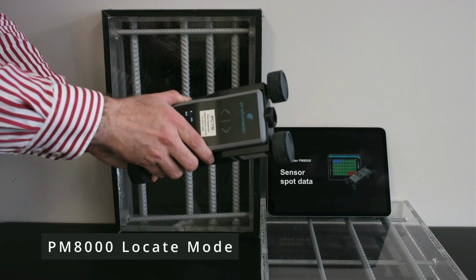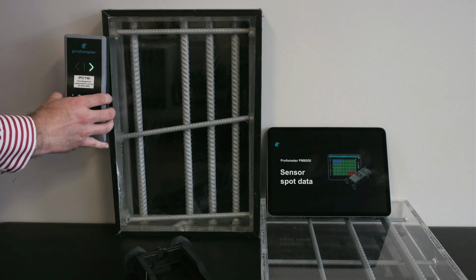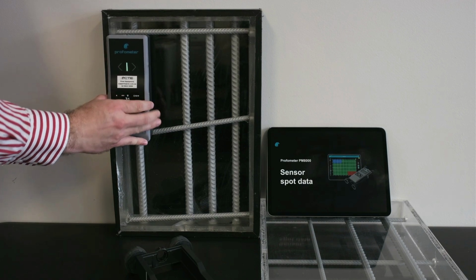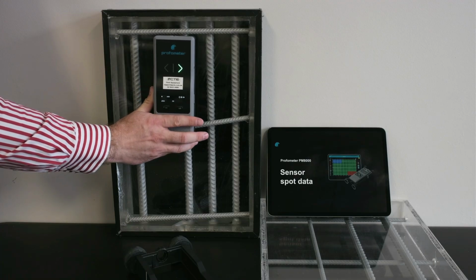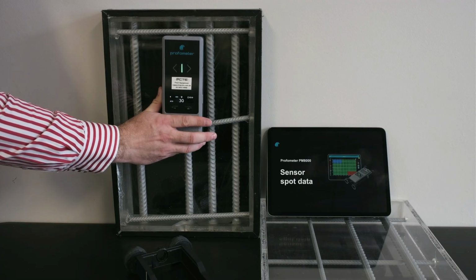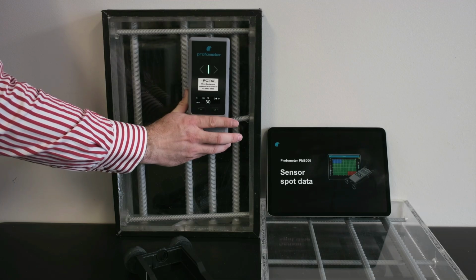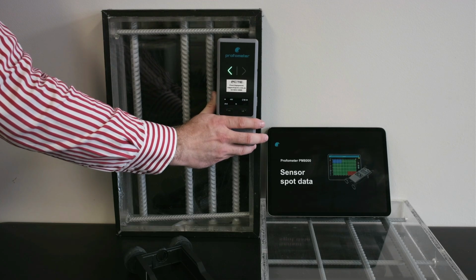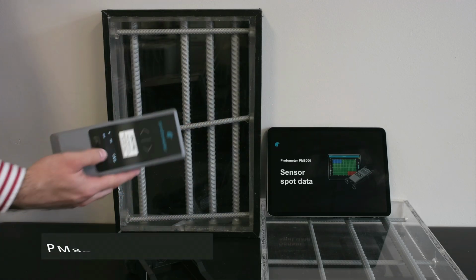Firstly, just pure bar location on the PM8000 cover meter. It will detect the presence of bar, and when we line up on top, we see the center of that bar, and then we can use that to find the centered position. And in this case, because I can see it, I don't need to know the location of the horizontal bars. But if I was doing this really properly, I'd have found both of those and done a few chalk marks before I took my numbers off.